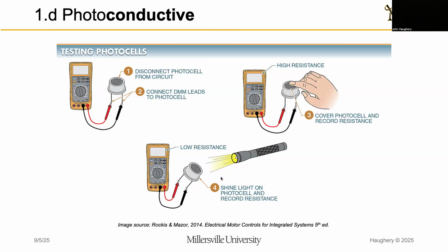And that's how we can troubleshoot whether the resistance is actually changing. If we see no change in resistance between no light versus extreme light, then we can assume that the photoconductive element is not functioning properly. And that's when we go pull out a new one.